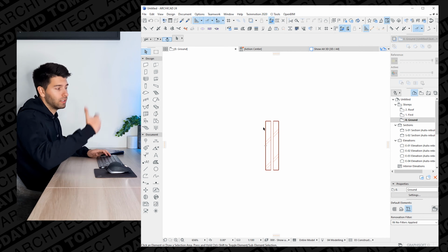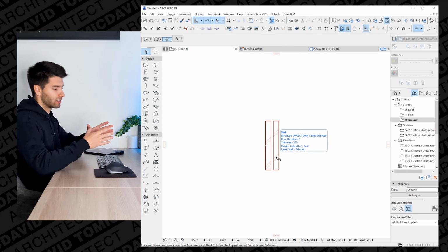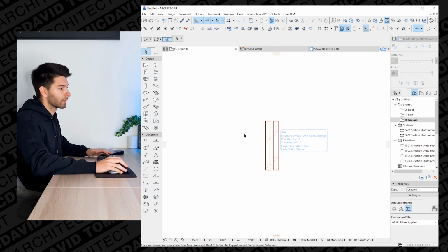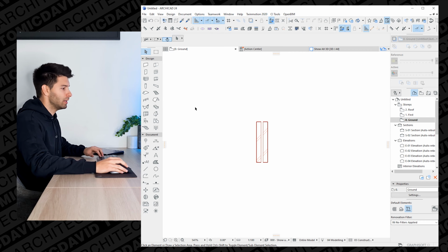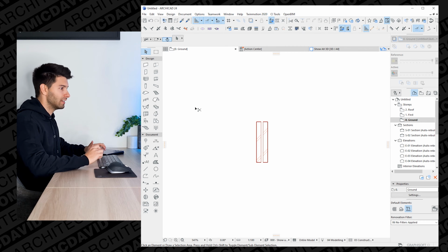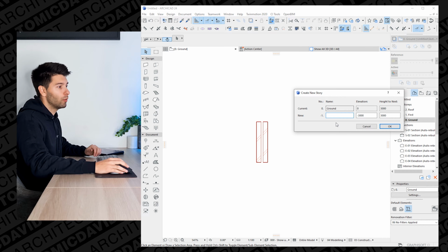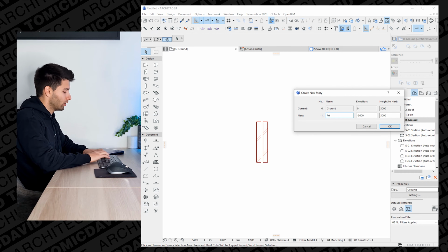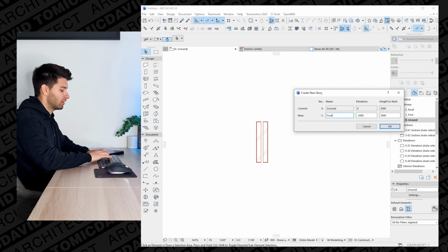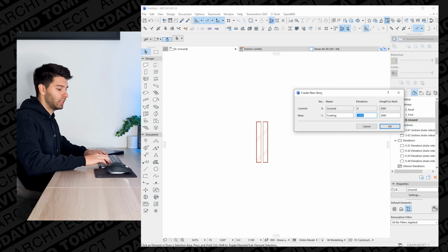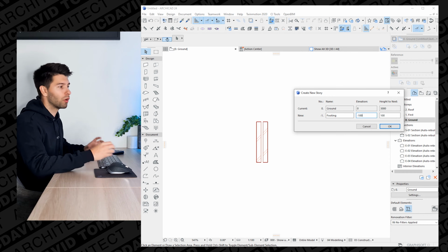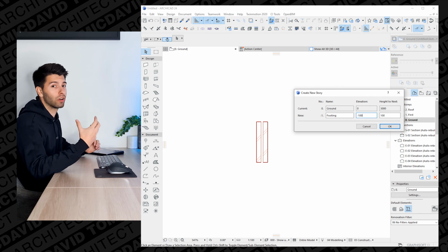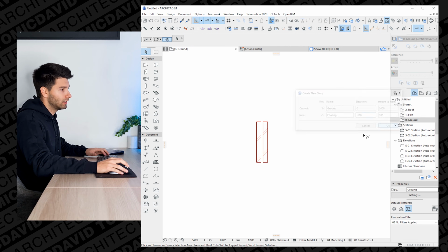Now with brick coursing, obviously you want to stick to brick coursing. A size brick is very typical, so 1 meter probably isn't achievable, but that's not what we're talking about today. The next step is clicking Control and the down arrow, which is going to open up a new story setting. I'm going to call this footings, and I'm going to go minus 100mm in this case, because we're going to draw the slab as 100mm and we're going to draw our footings in 2D. So let's click OK.